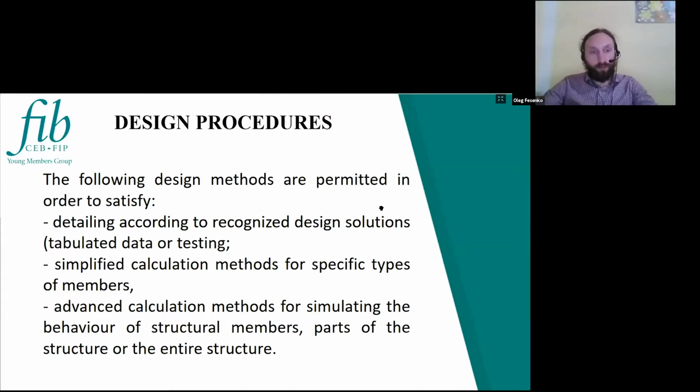Now we can talk about the design procedures. A full analytical procedure for structural fire design would take into account the behavior of structural system at elevated temperatures, the potential heat exposure, and the beneficial effect of active and passive fire protection systems, together with the uncertainties associated with these three features and the importance of the structure, consequences of failure.